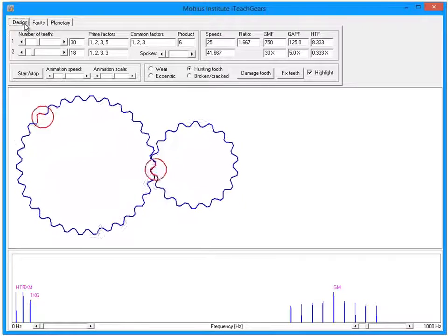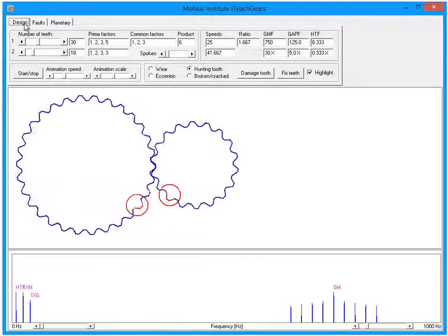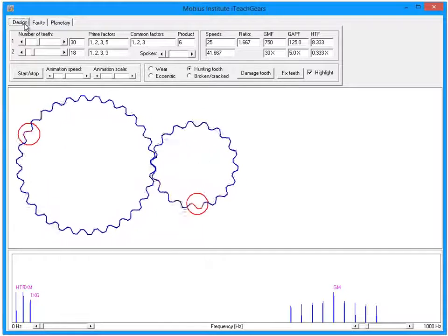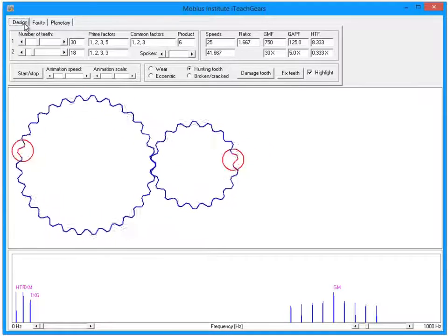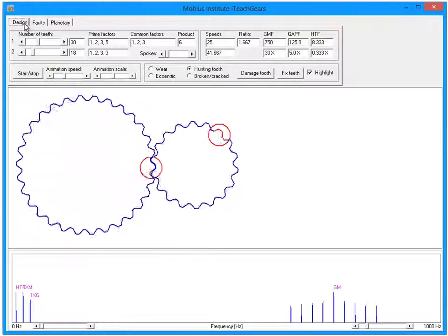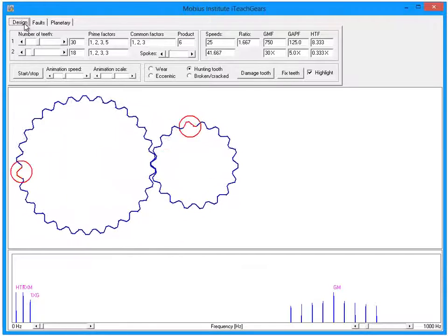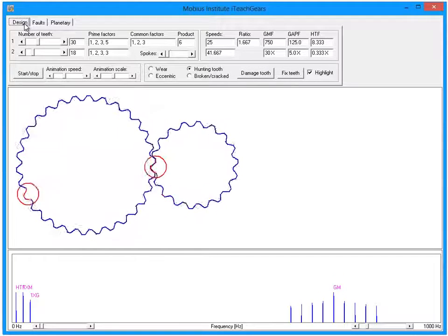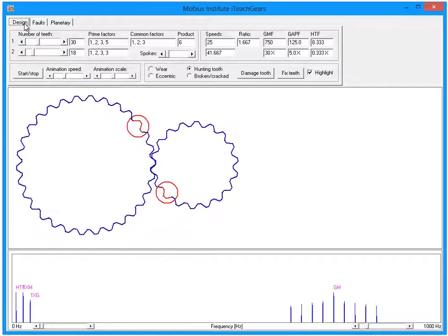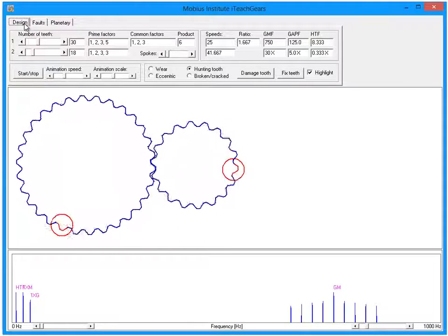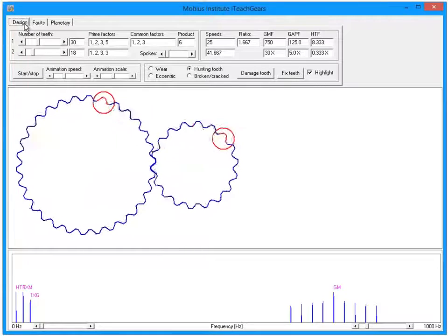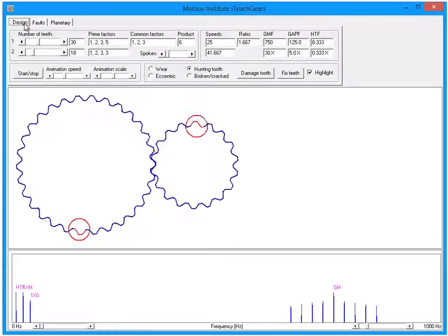So again, if we go back to that possibility that when the gearbox was transported, two teeth were mating at the time and they were damaged, then you can get a particular source of vibration every time those two teeth come back into mesh. That's going to be the worst vibration just when those two teeth come into mesh. When those two teeth mesh with other teeth, there's going to be a heightened amount of vibration because the teeth aren't perfect. But when those teeth come into contact with each other, then the vibration is even worse. And so you may hear this low frequency kind of growling sound coming from the gearbox, and this could be the source of that vibration.